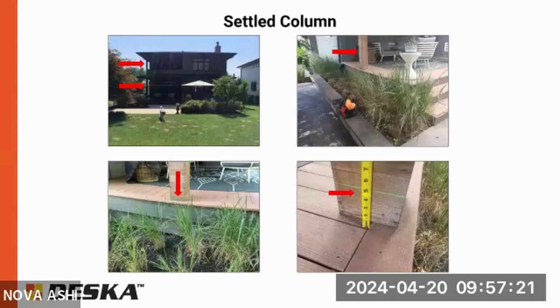So the building officials typically require, if you're building a foundation within 5 feet of a structure, the bottom face of that footing has to be the same elevation as that structure. So you can't put a column in the ground 4 feet from your basement foundation and just dig it down to the frost depth of 24 or 30 inches. You need to go to wherever your basement foundation is. So if you're going to install a deck, the footing of that deck needs to be down as deep as the adjacent structure, if it's within 5 feet. Otherwise you're installing a footing in the fill and it's going to settle quite a bit.